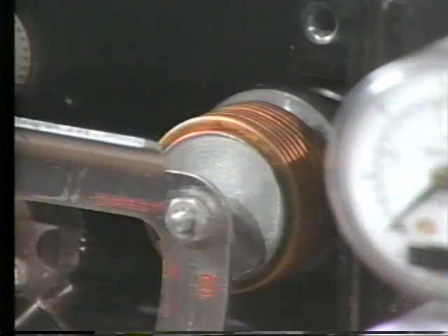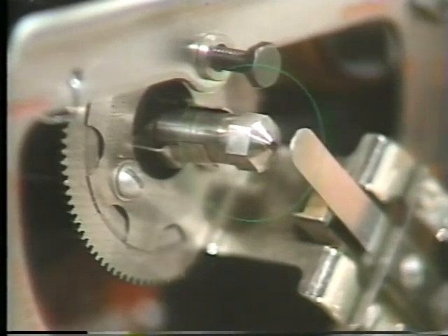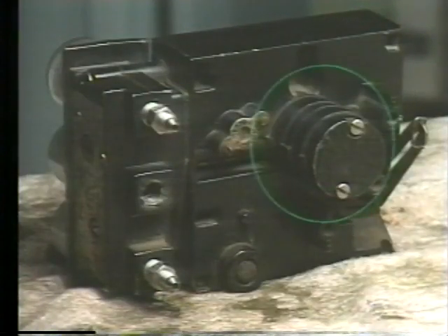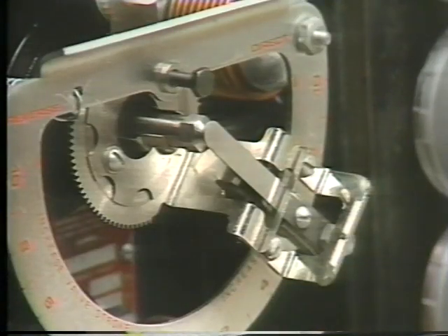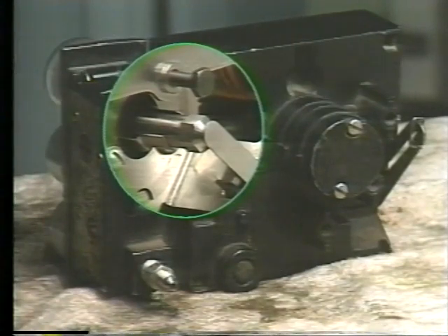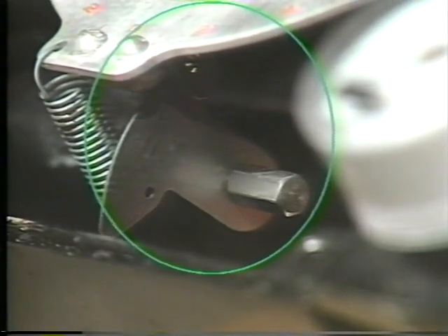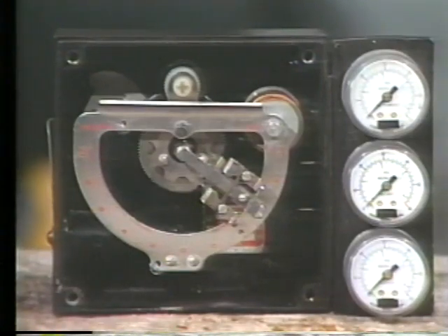In this positioner, the input mechanism is this bellows. The error detector mechanism is this flapper nozzle arrangement. And combined with it, but hidden inside this part of the positioner case, is a pilot valve type of device. The flapper nozzle arrangement, when combined with the pilot valve, is called a pneumatic relay. The output or balancing mechanism is this cam and cam follower with its associated linkage. Let's see how these self-balancing mechanisms work, and as we observe, we'll identify the various parts of the positioner.